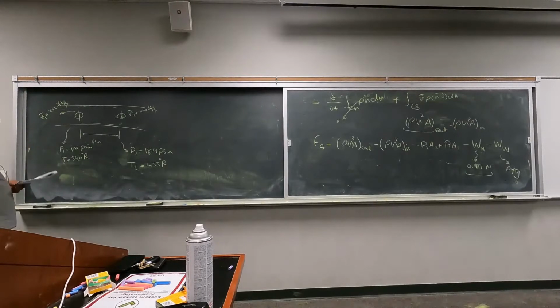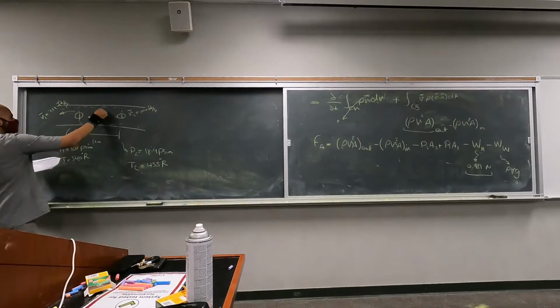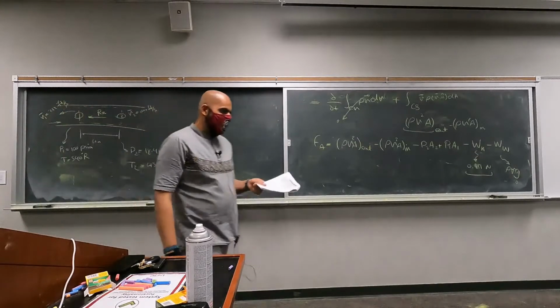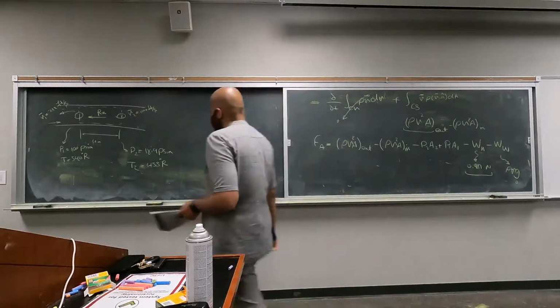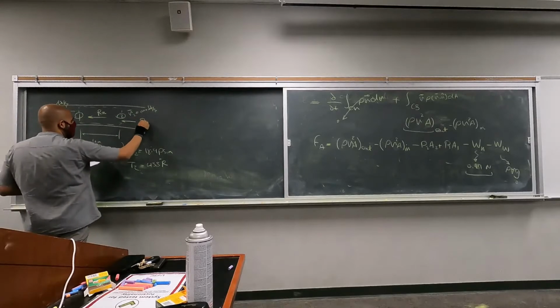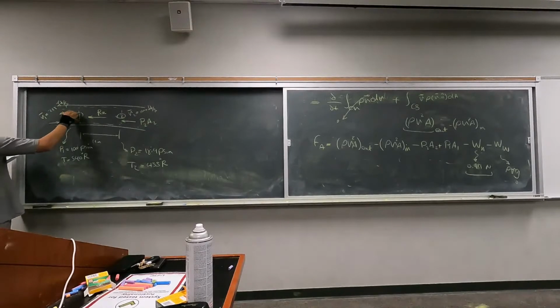So what are the forces that are present here? One is the friction force, opposite to the flow direction. The flow is going in this direction, so the friction force is going to be in the opposite direction. This is something that you had on the exam as well, right? We call the shear stress negative, which means that it is in the opposite direction of the flow. Flow is going in this direction, friction force or the shearing force is going to be in the opposite direction. And then we have the pressure force on cross-section 2, P2A2, and pressure force P1A1.